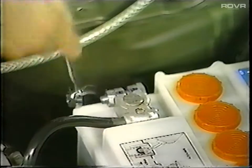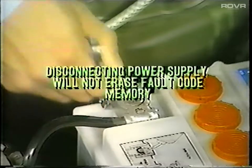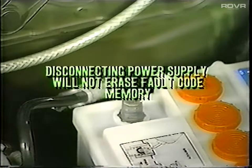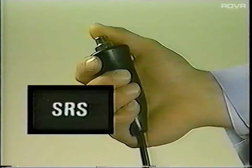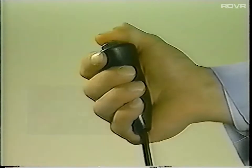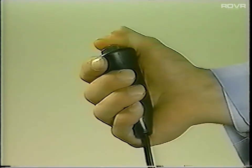The SRS has a hard memory feature, meaning that disconnecting the power supply will not erase fault codes stored in the memory. Erasing must be done as follows using either a jumper button or impulse counter. First, you must recall the fault code. After the fault code is displayed, push the impulse counter or jumper button for 7 seconds.